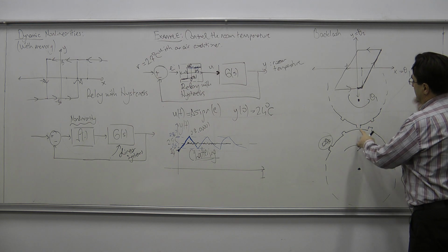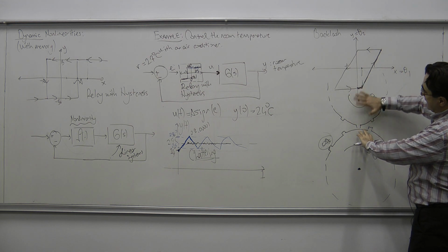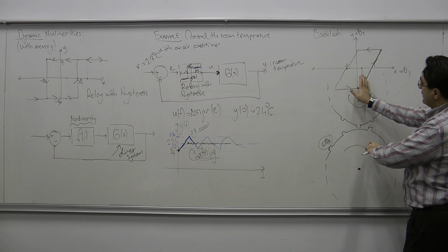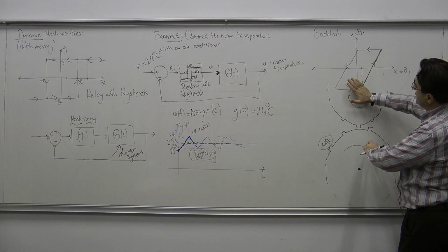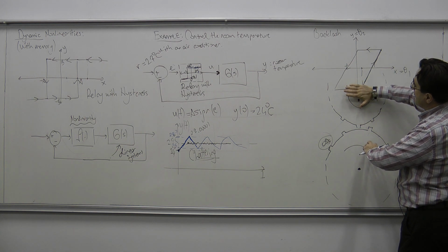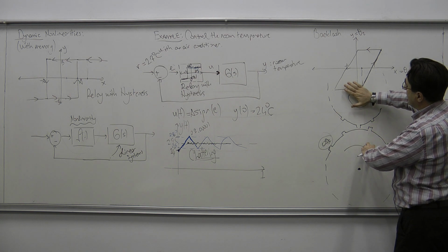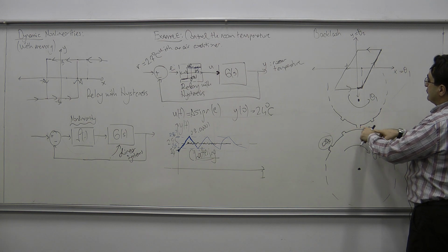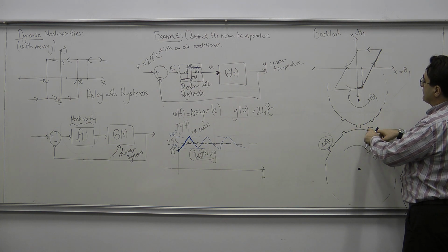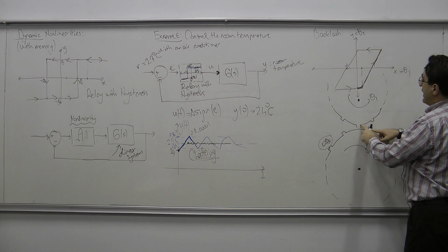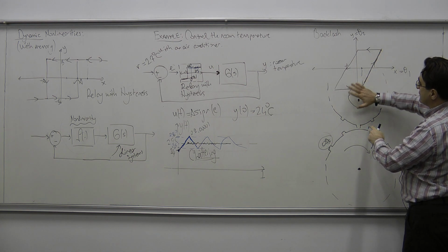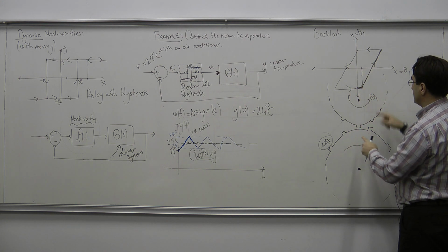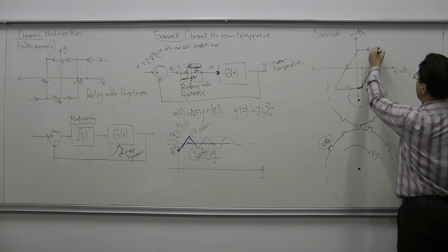So suppose that after some turning, we turn the first gear back. After turning the first gear just a little bit in the counterclockwise direction, suppose that I start turning it in the clockwise direction. In that case, these two cogs start from the touching position, but as soon as I start turning this first gear in the clockwise direction, they are going to be separated, and θ2 is going to stop turning.